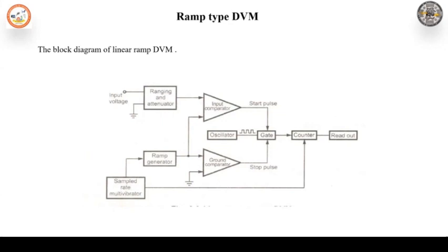The typical value is 5 measuring cycles per second with an accuracy of plus or minus 0.005% of the reading. The sample rate provides an initiating pulse to the ramp generator to start its next ramp voltage. At the same time, a reset pulse is also generated which resets the counter to the 0 stage.